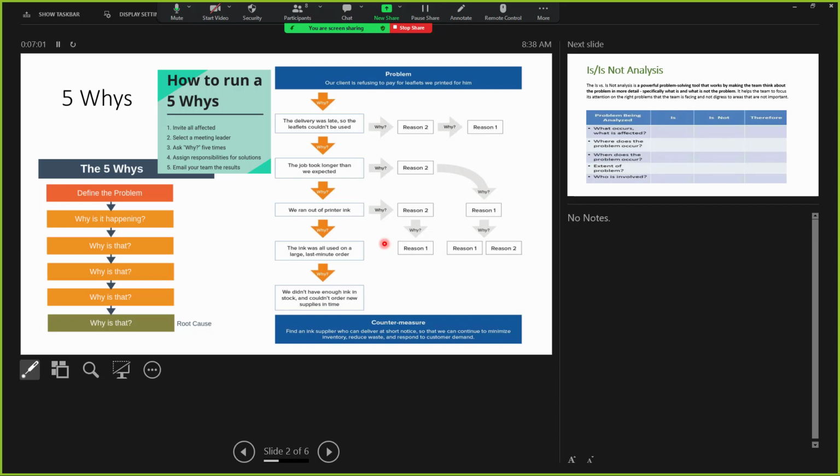If you want to break down your project, you might be going until you reach, for example, the smallest screw in the project. As you have a rule of thumb of 80 hours, if it's less than 8 hours, you're not breaking it down further. For example, fixing this door will take 8 hours only, so this will be a task. Or fixing the 3 doors in Excellence Training Center while constructing will take 8 hours, so you will not be breaking down for each door. You will say the task is fixing the doors in the project.